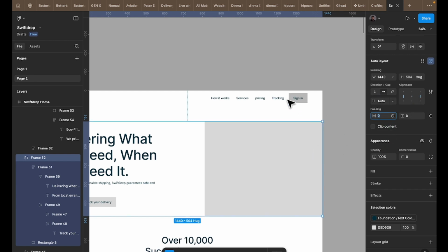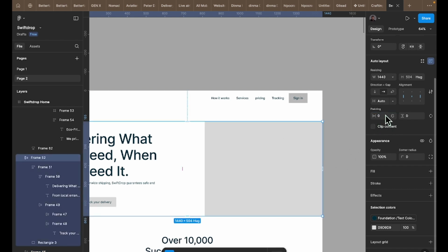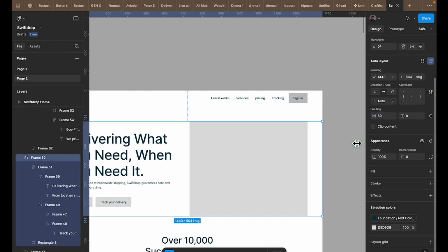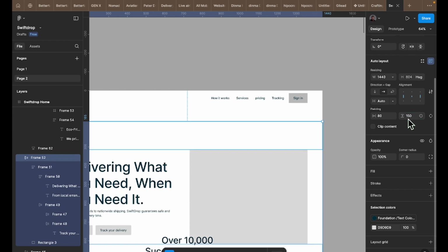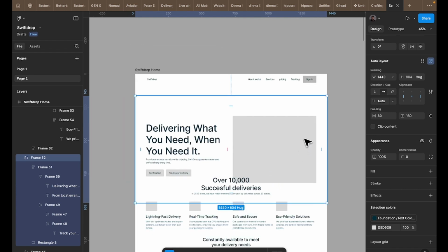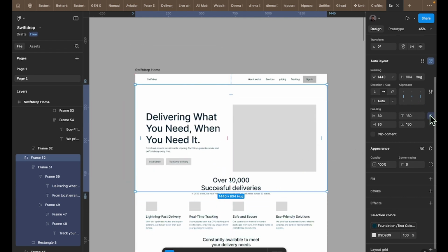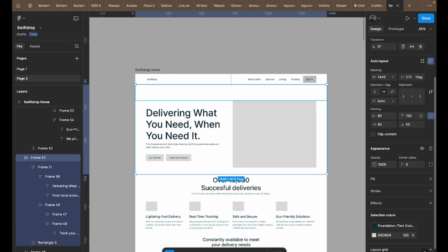And what happens is you can see, okay, the spacing for this one was 80, and I want to get a straight line. So you can decide to say, for this place, we also want 80. And for top and bottom, we want, let's say, 150. So this is what happens. We adjust it here. We're going to be readjusting, that's fine. You can actually also edit that. See, for the bottom we want just 50, and this happens. You can see for the top we want just 120.